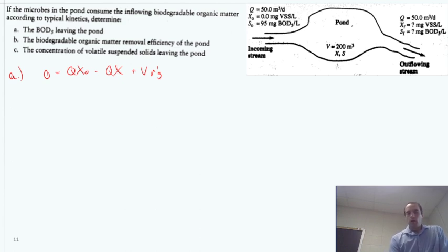All right, so I'm going to go ahead and work with you from here. So essentially, the problem is a bit counterintuitive. We have an issue where we need to find S and X, but they're both changing, right? So we really need something to let us simplify and prevent us from trying to solve for two things that are both changing simultaneously. So when we take a look at the mass balance, the counterintuitive part is that since they rely on one another, given that our mass balance happens to be the steady state mass balance with CSTR, we can get one of these to cancel out.